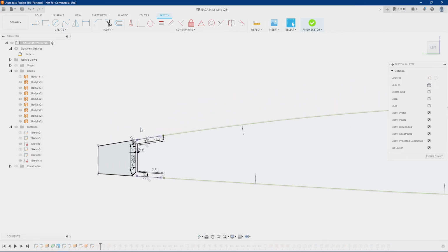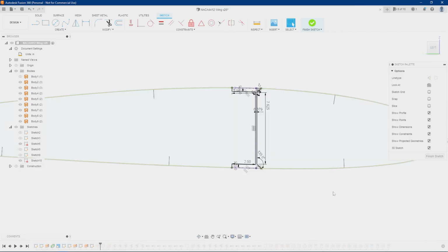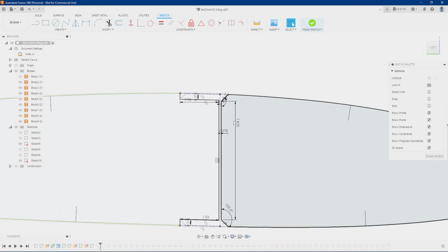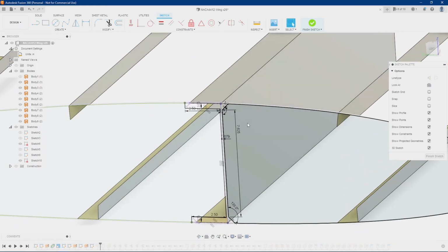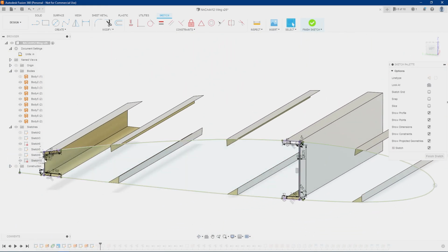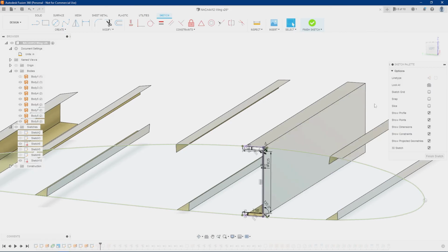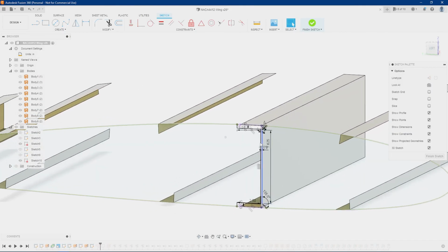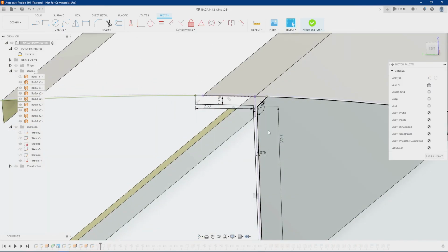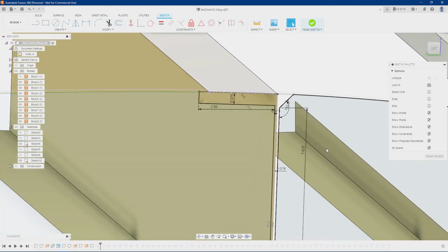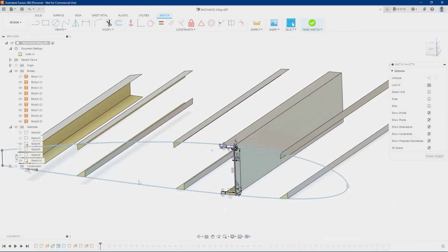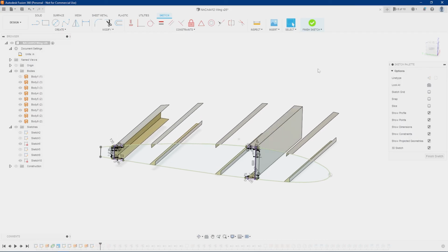So essentially we're cutting the ribs into 3 pieces so that the spar can be one continuous long piece, right? If we wanted the rib to be one big piece and the spar to be cut into different sections, then all of that bending load of the wing would have to go through fasteners, whereas when we cut the rib instead, the spar is just one long piece that runs along the length of the wing, which is what we want.